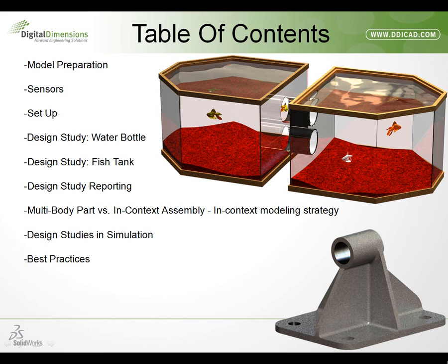After you have your model prepared, there's one more requirement for design studies, and that is sensors. Sensors are like timers or watchdogs that will keep track of your model based on certain criteria. The design studies can read this criteria and either pass or fail your results based upon those sensors. Once our model is prepared and we have our sensors ready to go, we then set up the design study.